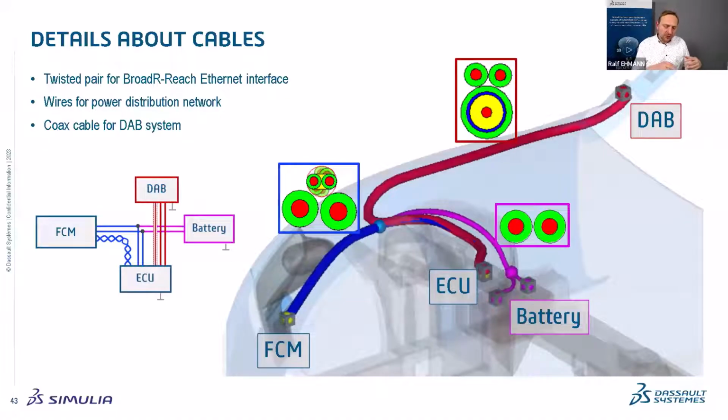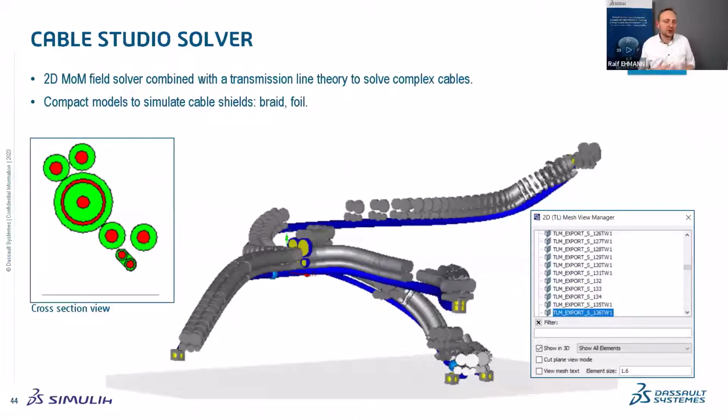And it's important that for cable simulation, as long as we are concerned with crosstalk, as long as we are concerned with line impedance calculations and don't require fields, we don't need to use a full wave method. In the radiated emission example, of course, I require fields. I need to calculate the field at a certain distance. This is where I need to go to a full wave solver. But as long as we would like to just look at the couplings between cables, near field couplings, we can use a so-called transmission line method.